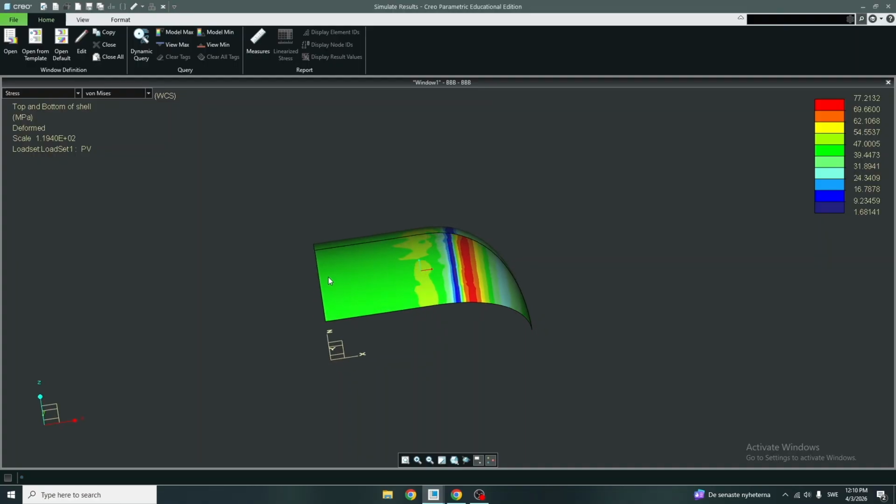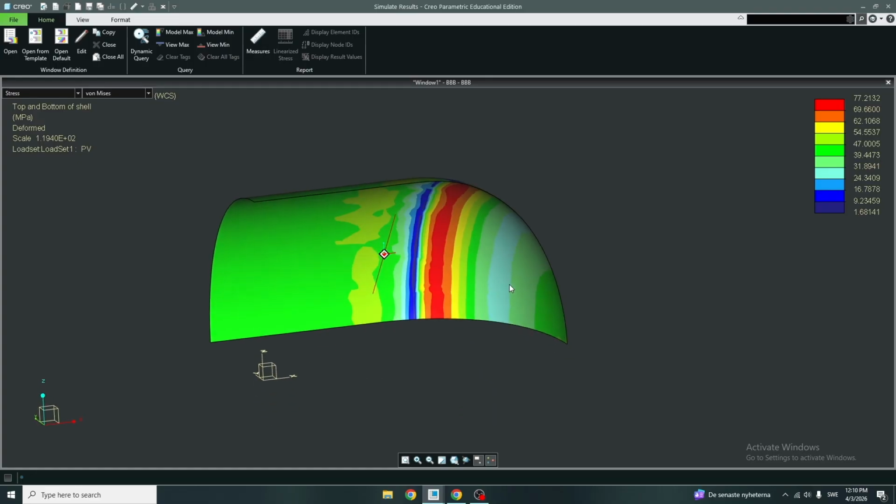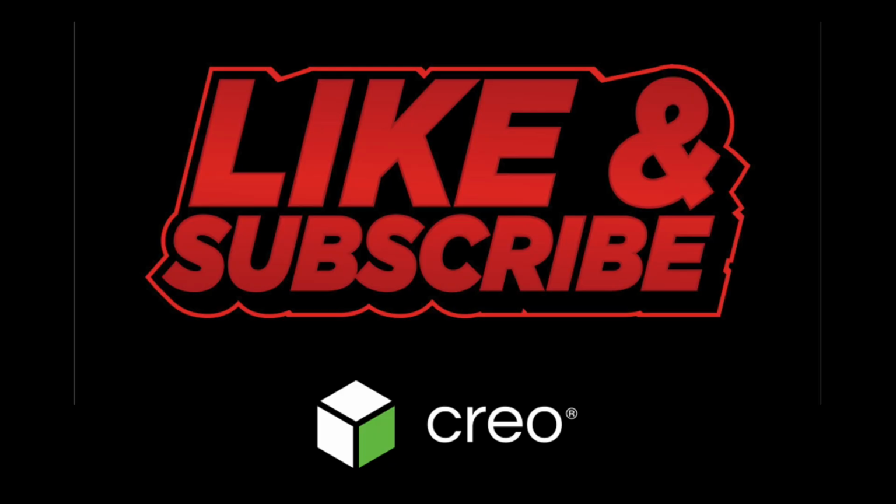You can divide the surface and maybe fix one part of the cylindrical surface that are going to represent something that is holding them. But I used the boundary condition for the entire cylindrical part. And you apply the load, you do a good mesh, and you run the study. As easy as that.